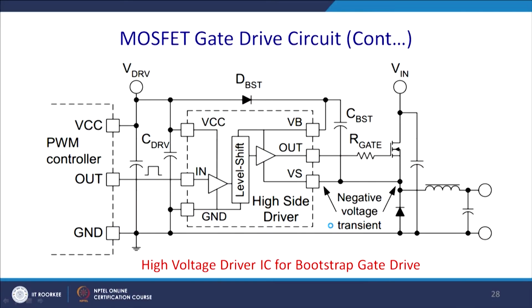So, we require faster turn-off for this kind of application. Another aspect comes into the picture: bootstrapping. This issue arises when this MOSFET is turning on, and we must consider what the level of the voltage should be. In an inverter leg, the lower MOSFET does not have that problem. Once it is turning on, the voltage of the drain goes to 0, and the source is always 0, but the reverse happens for the upper MOSFETs.